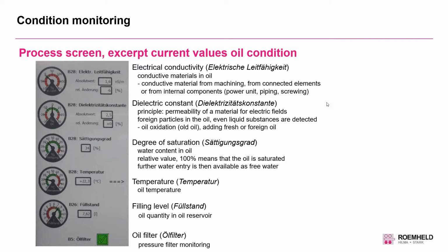And as an additional item, the oil filter, which in most cases is part of the hydraulic unit today, is important. The oil filter is normally monitored by the pressure within the filter, which is detecting the filling rate of the filter itself. Okay, the next slide, please.